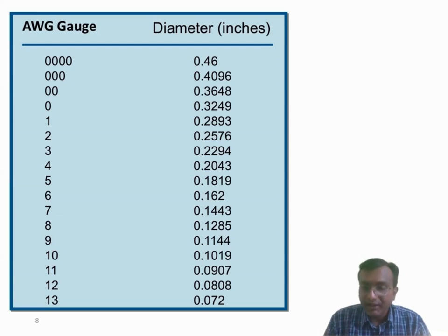If we use aluminum, it is a cost effective way. The cost of aluminum is less compared to copper, but we face problems with the operations, such as the energy losses being more in aluminum. So it is better to go for copper wires. Initially it will cost you more, but the running and operating cost of the systems involved will be less in the case of copper.